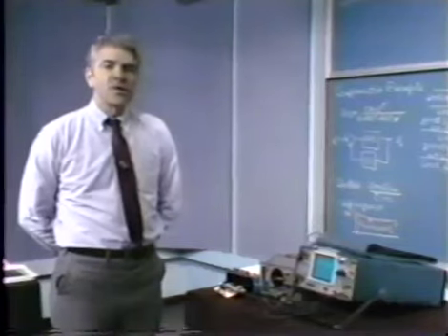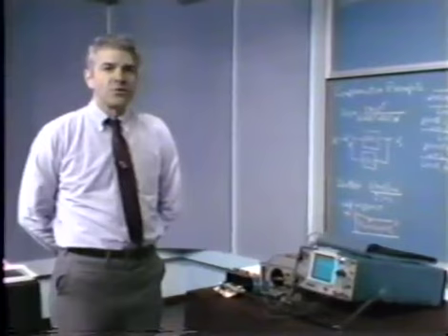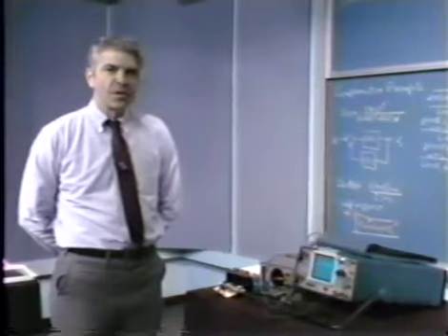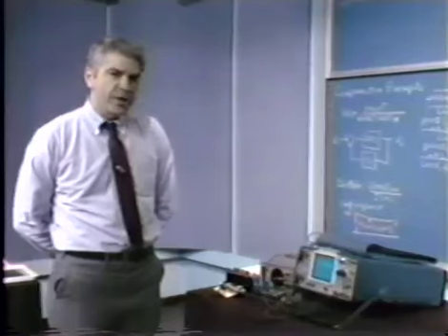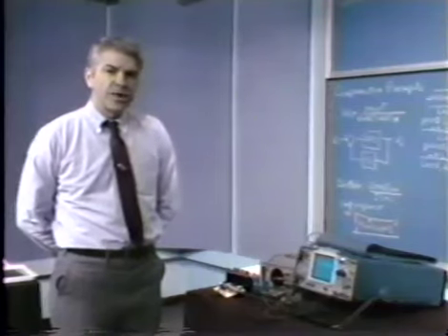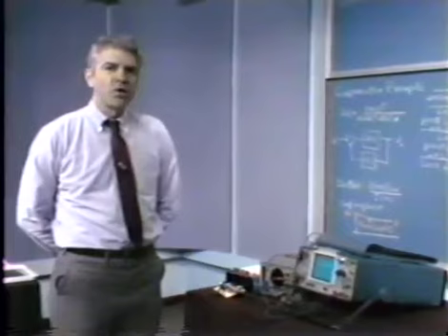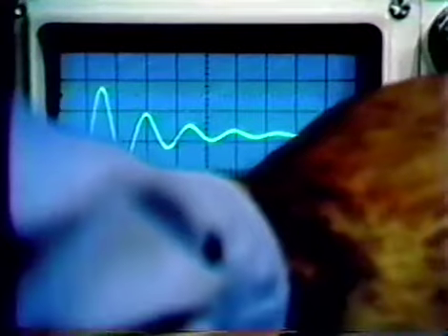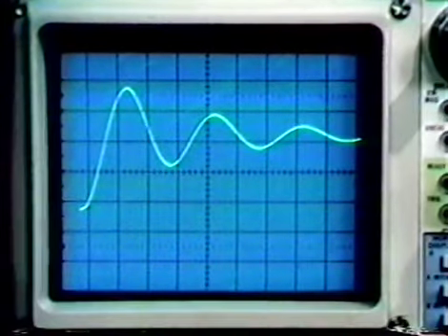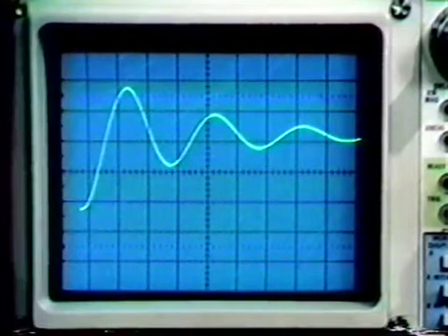Here we have 14 degrees of phase margin, close to 0, at least uncomfortably close from a feedback system point of view. And so we'd anticipate that the ring frequency associated with the step would be somewhere on the order of 4 kilohertz. And we see that. Let me speed up the time scale just a bit. One major division horizontally now corresponds to 100 microseconds.